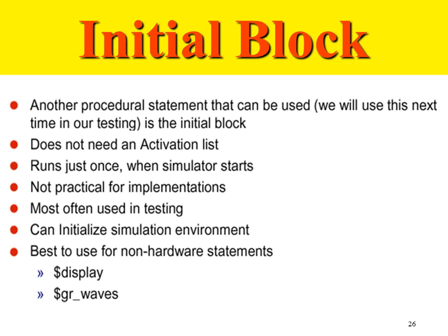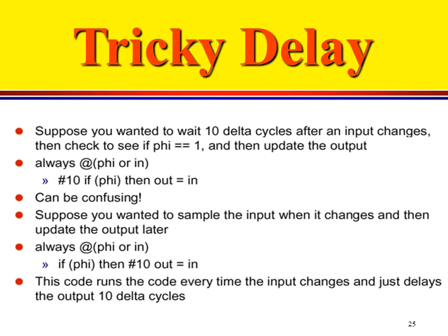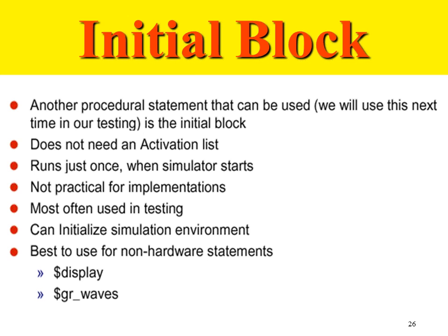So would we say the initial block is where we write the variables and show how they are connected, like maybe say these are inputs and these are outputs? That can also be done as a part of the port declarations that we'll see later on. So input-output declarations are done somewhere else, not in the initial block. We are talking purely about logic here.